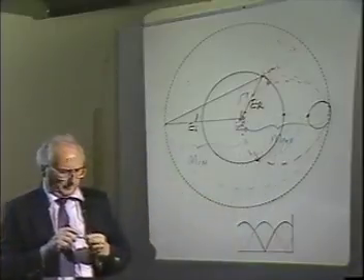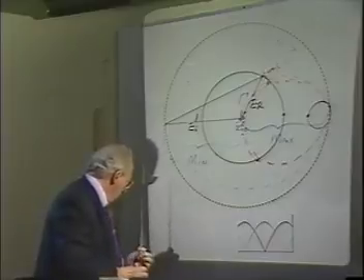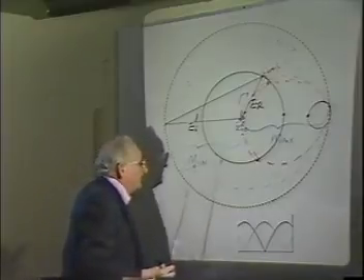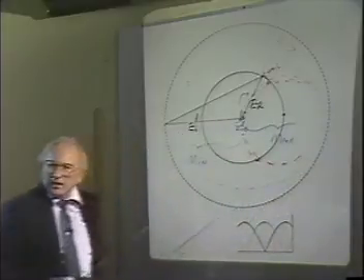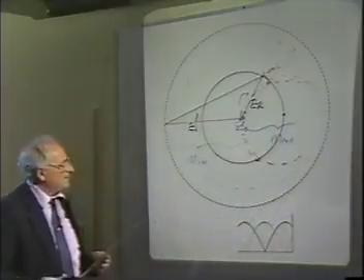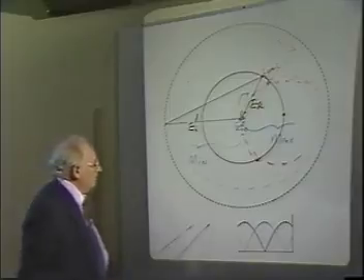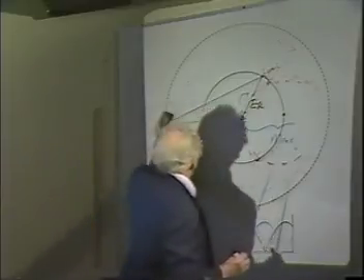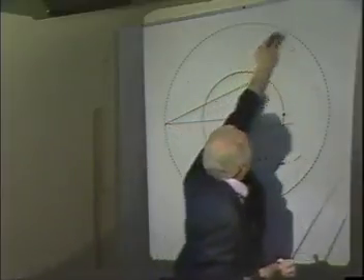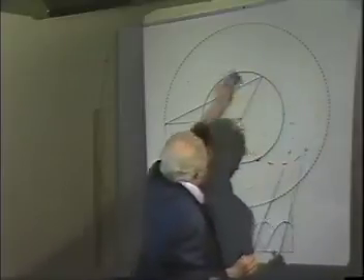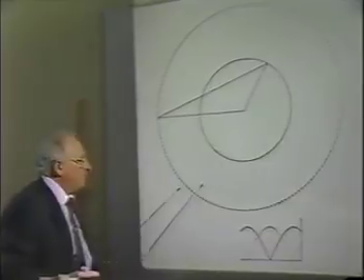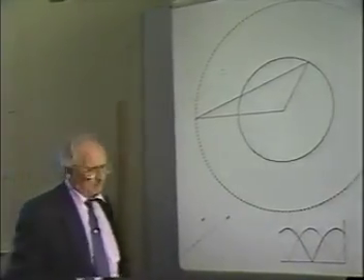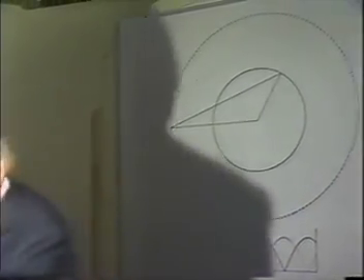Okay? 800 ohms, what would the VSWR be? 50 to 1, pretty high, right? Okay. This will be convenient for working some problems out later on.